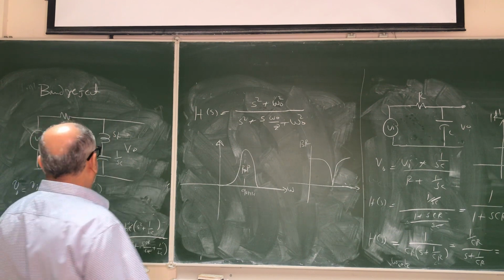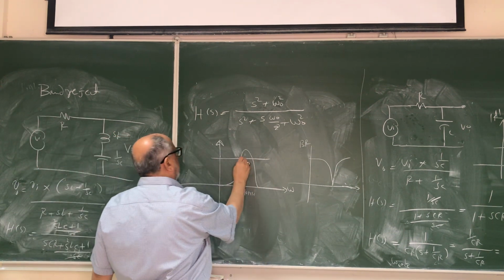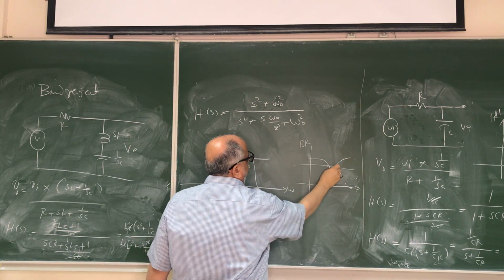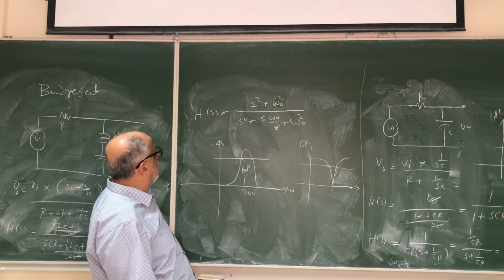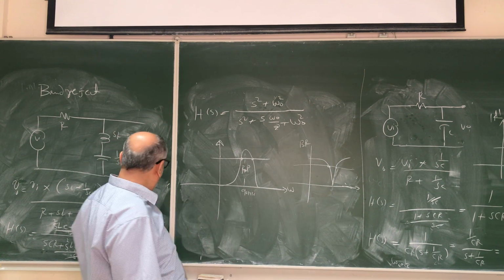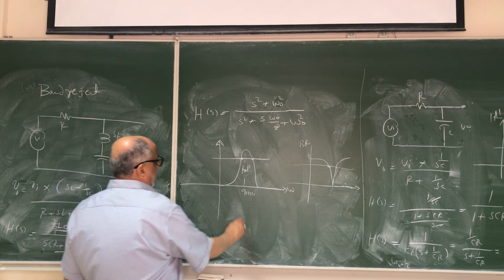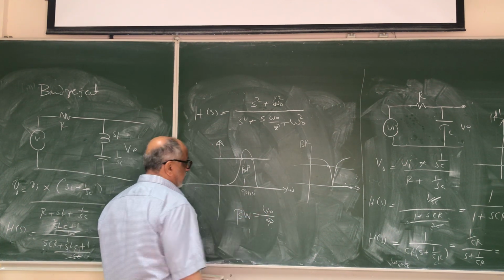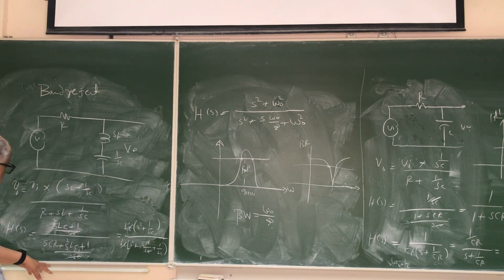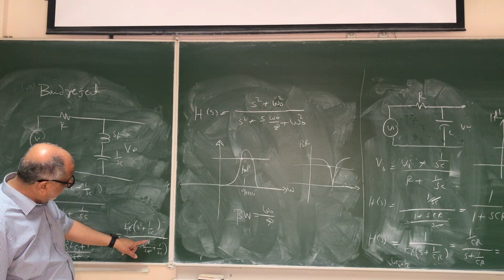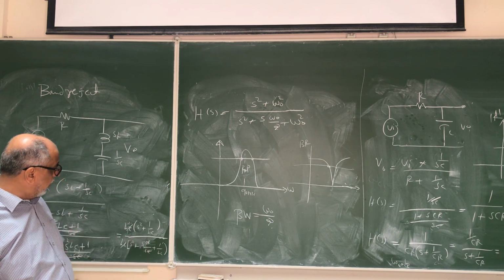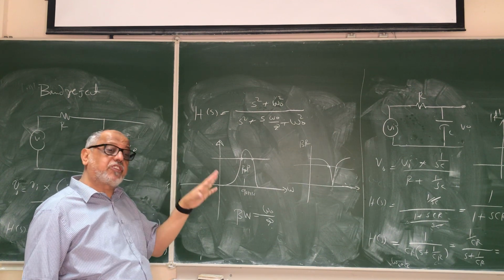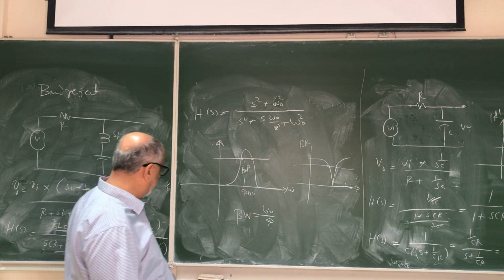Then we have some details, like what will be the half power. So this is the minus 3 dB frequency here. Same thing here, what will be the half power frequency here. So we have to find these values and the bandwidth, and we know that the bandwidth is equal to omega naught over Q, right? Now with this term you can find the other parameters, and we know that the bandwidth, which is R over L in this case, is omega over Q. You can design your filter so that it meets certain specifications you have in your mind.